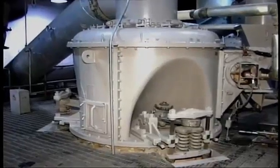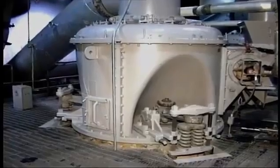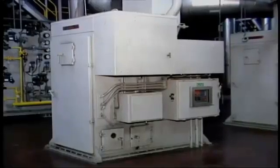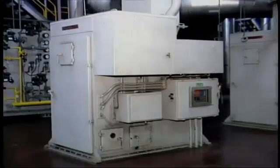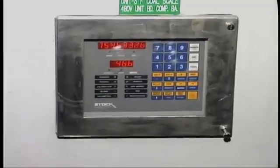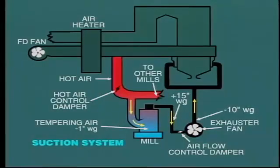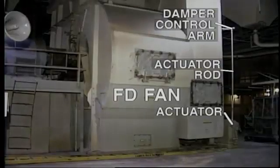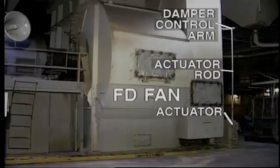Well, this is done by controlling the quantity of coal and primary air entering the pulverizing mill. Coal is fed into the mill from storage hoppers located above. Adjustable feeders control the quantity of coal which is fed into the mill. Primary air can be controlled by adjusting the speed of the fan or by regulating dampers. Of course, as primary air and fuel are adjusted, the quantity of secondary and tertiary air must also be controlled at the forced draft fan.